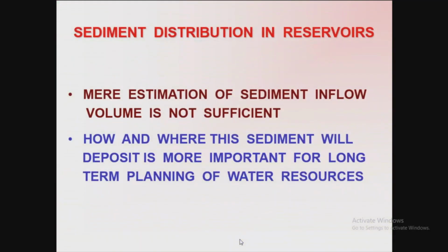Now, as I told you, a bare estimation of sediment inflow into the reservoir volume is not sufficient. How and where this sediment is deposited is more important. If it is deposited in live storage, I am more concerned about that. I am not very much concerned if it is deposited in the dead storage. How much volume is deposited is not important. Where it is deposited is more important.